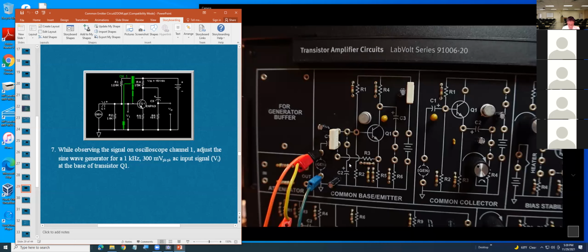Mr. Pham, for VC, since you have that broken line over there where R6 is, it won't measure that area. It'll just go past R5. Is that correct? Now the thing they did for the AC setup. Yeah, I'm saying, for DC, when you measure VC, it won't measure that part, right? VC, they don't care here. The thing is, C3 here is DC blocking. Yeah.